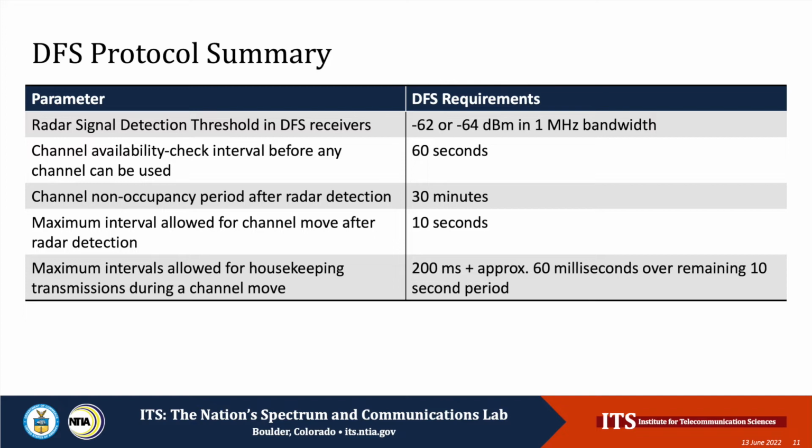If a channel has been occupied and the radar signal is detected in the channel, then the channel has to be vacated and may not have any attempted reoccupancy for the next 30 minutes. The maximum interval that's allowed for the channel move after radar detection is 10 seconds. In other words, if a radar pulse is detected in an occupied channel, then that channel has to be vacated within 10 seconds.